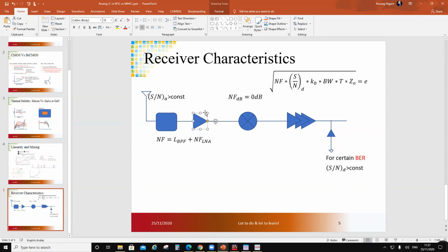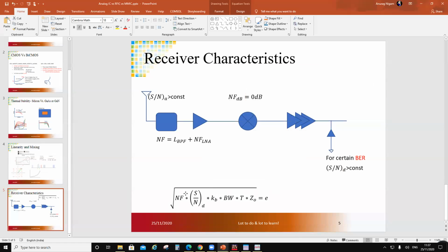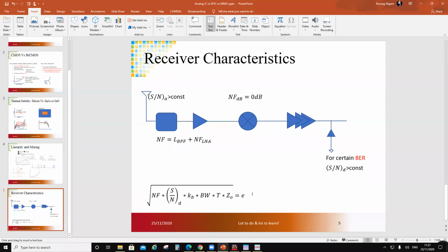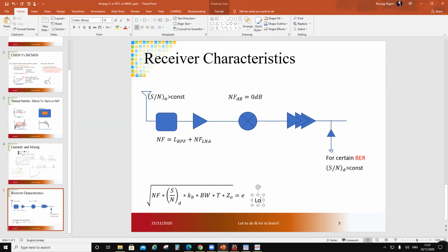So what it means is the following. So in this case, the critical thing is, we know which is the lowest voltage. So this is 1. This is referring to the lowest signal voltage. Okay, so this we have figured out, and this we have figured out that there has to be NF, and for NF we know that the gain of the LNA should be very large, right? So that the thing over here doesn't matter. But very large is not possible because there is another constraint. The other constraint is the distortion or TOI.